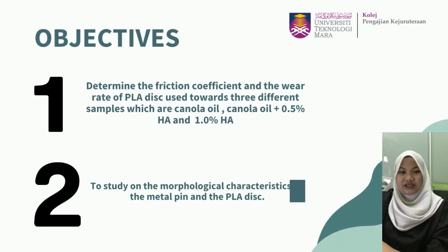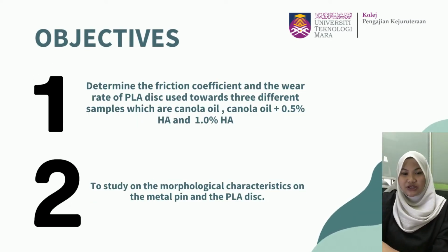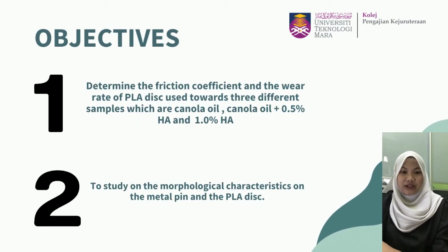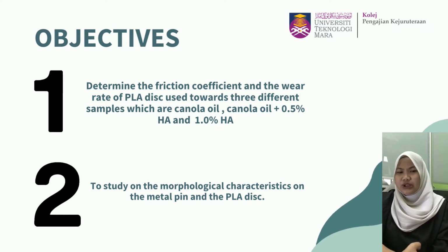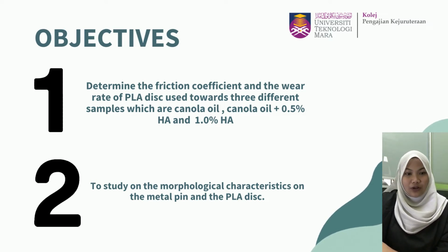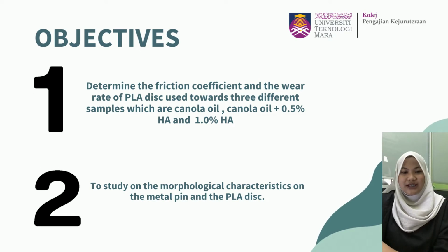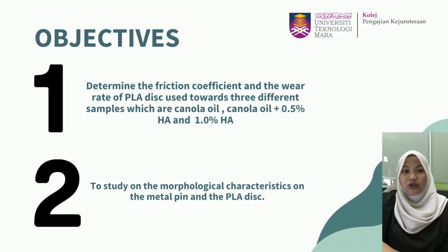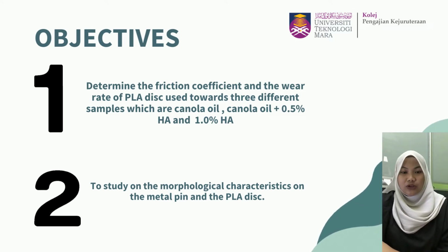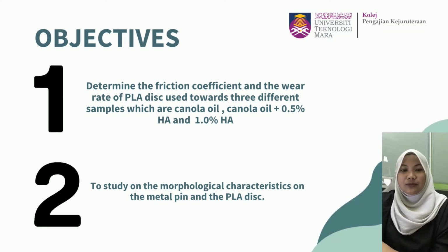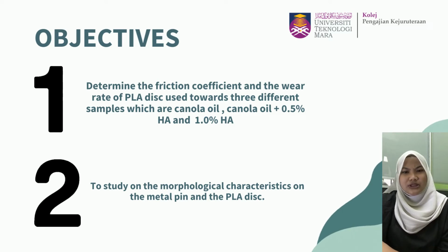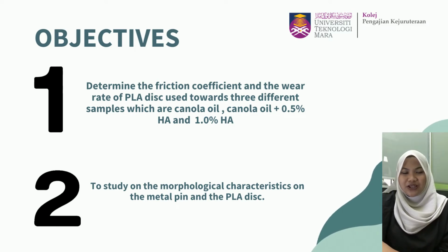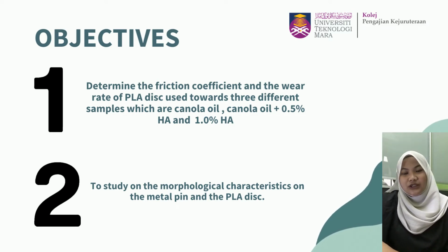The objective of this study is to determine the friction coefficient and the wear rates of PLA used toward 3 different samples, which are canola oil with 0.3 hyaluronic acid as additive, canola oil with 0.5 hyaluronic acid, and canola oil with 0.8 hyaluronic acid. This objective can be fulfilled by having a reliable result of at least 0.03 for the friction coefficient after dipping on these